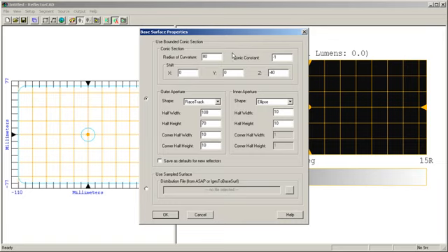The base reflector in this case is going to be a very simple parabola, which has a radius of curvature of 80 millimeters, and the focus of the parabola will be located at the global origin of my optical system. Additionally, I have the ability to enter some simple output aperturing of the reflector. In this case, it's going to have a racetrack shape with these following parameters. I will also have ReflectorCAD insert a hole of approximately 20 millimeters in diameter for which I can put in a bulb.